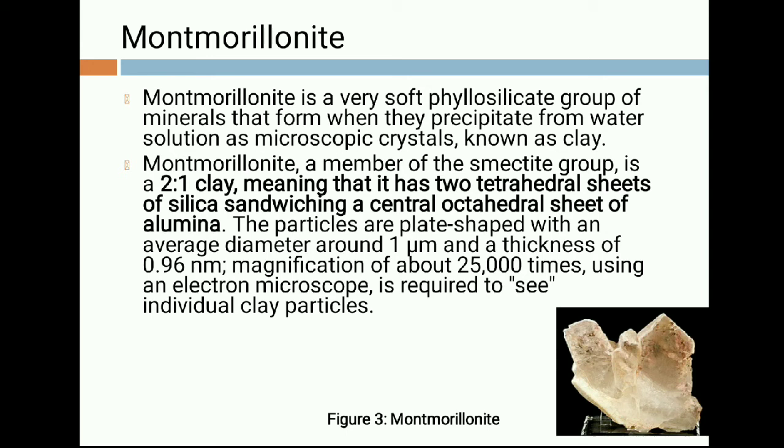The particles are plate shaped with an average diameter around 1 micrometer and a thickness of around 0.96 nanometer, at a magnification of about 25,000 times. Using an electron microscope is required to see individual clay particles. Means they are so small in size. For that we need an electron microscope to see these clay minerals present in the soil.